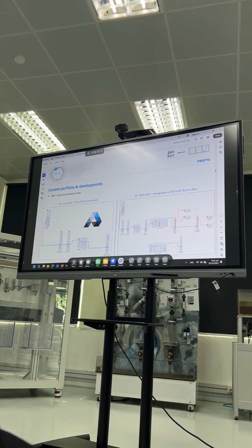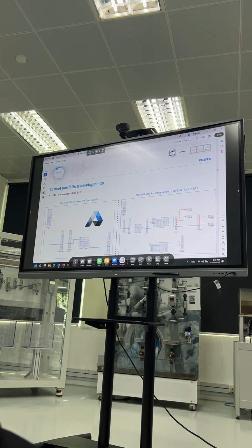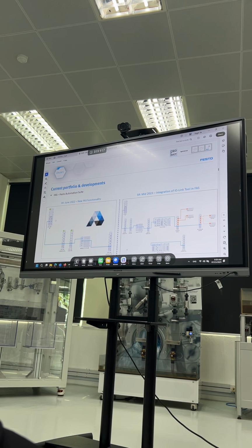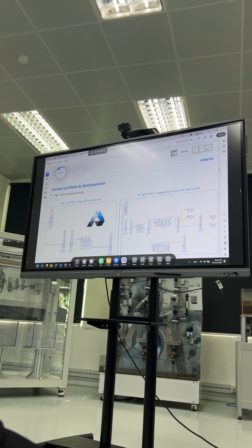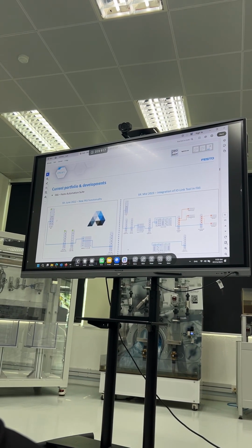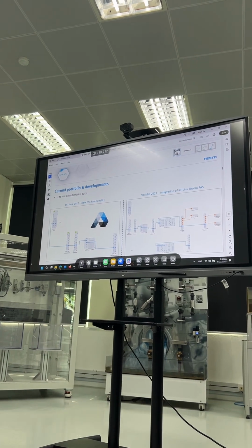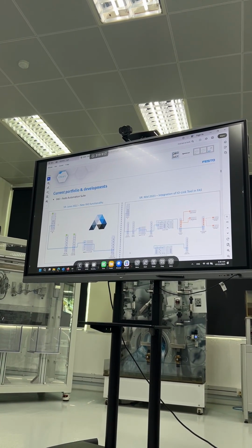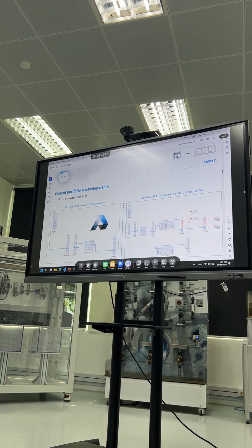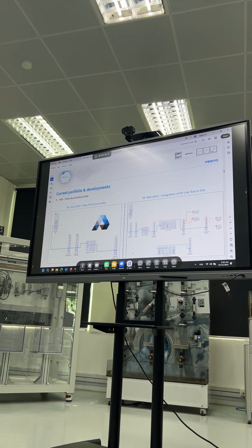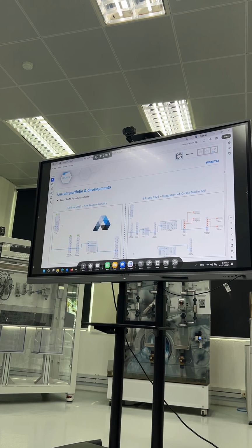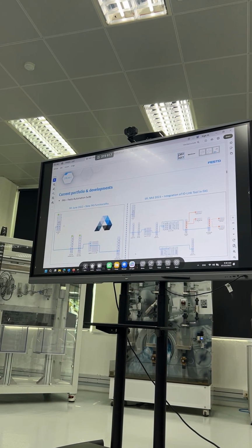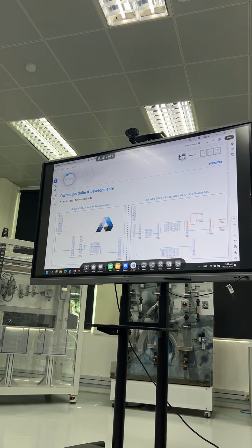This is important, especially when we are doing troubleshooting. For example, a customer claims that our IO-Link module is not working, but the problem could be coming from their PLC, where they did something wrong. We could verify that with the backdoor mechanism, connecting with FAS to control the IO-Link device to show them that it's working.